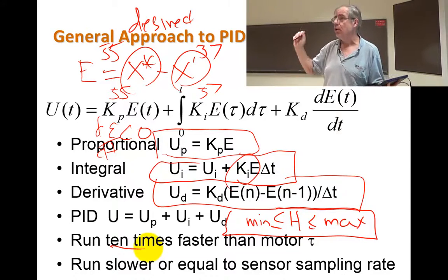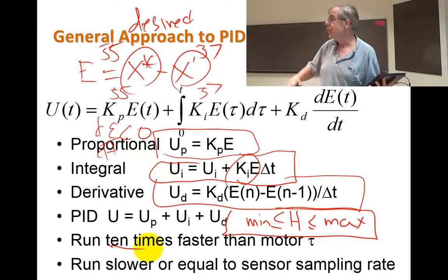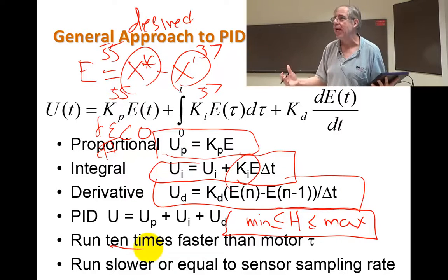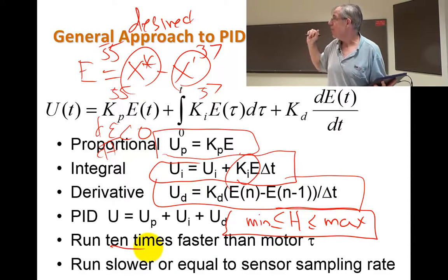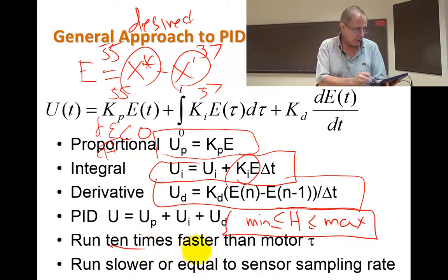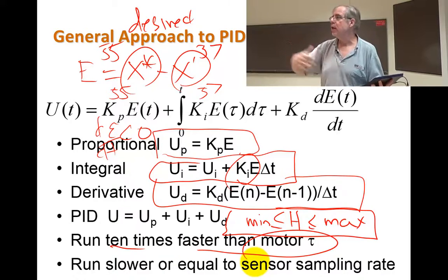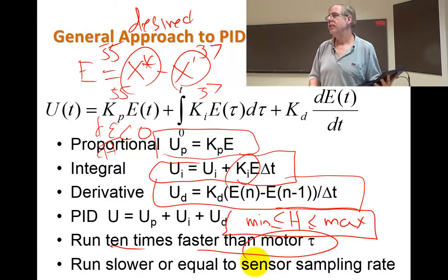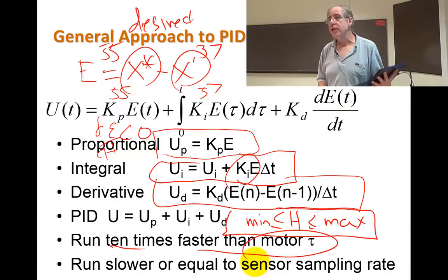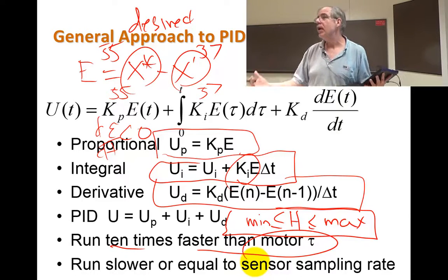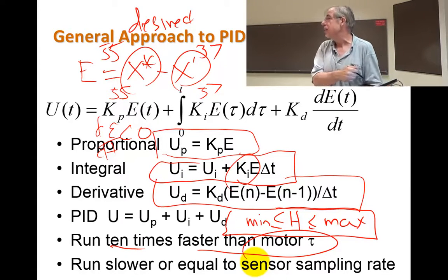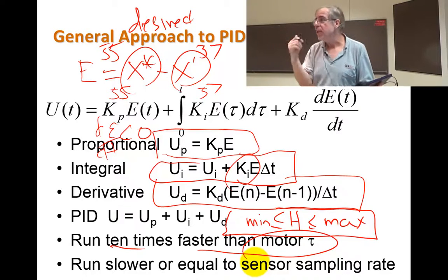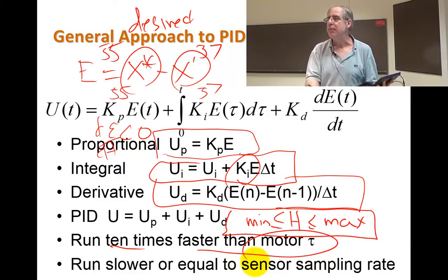It takes too long for the person in the back to say, would you please go faster? Would you please, you're going too fast, would you go slower? If you let the person in the back control the speed, you are running way too slow and you're going to oscillate from 100 to 0 miles per hour. You're going too fast, you go down to 0. Oh, now you're going too slow, and then you go to 100. Oh, now you're going too fast. And there's a rule right there. Your controller, the thing that's running the feedback loop, needs to be faster than the plant itself.